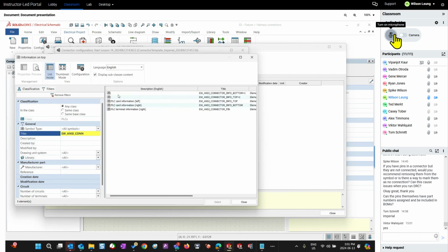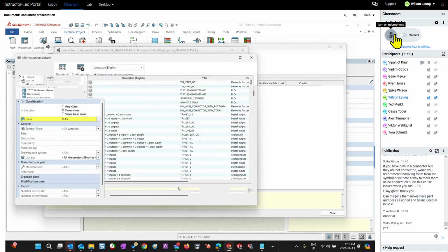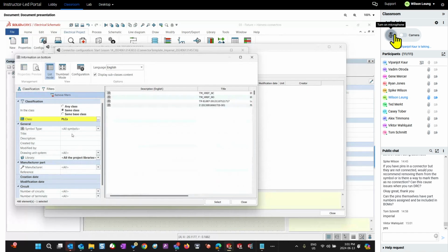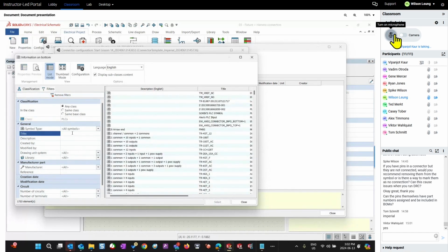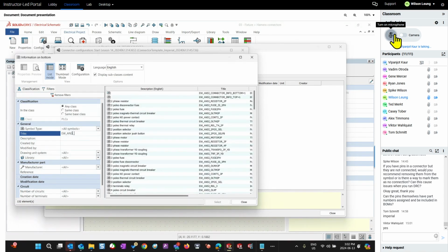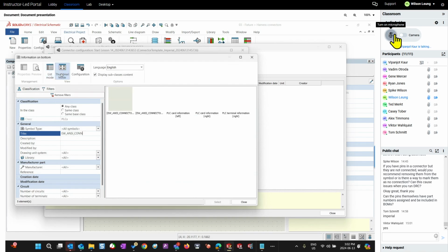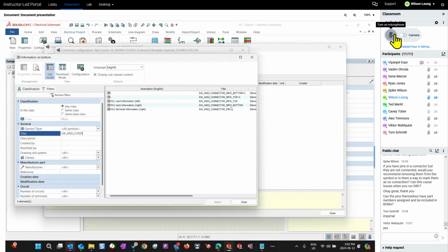So I'm going to check out my list mode, and the symbol I want is this top plus one. Double click, use this. It's going to show a component tag on the top. What do you want to see on the bottom? Search. And I need a similar symbol, remove filters. And I'll type in here EW_NC_bottom. So once I see a few different results, when I start typing in the name, I'll check the thumbnail mode or list mode to read a full name and full description in the list mode.